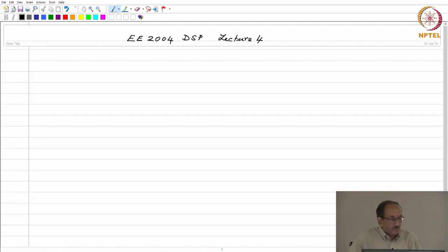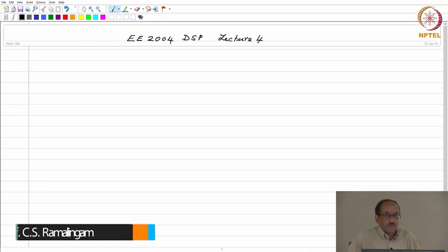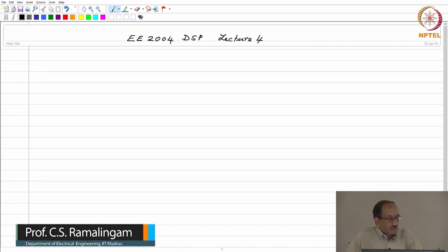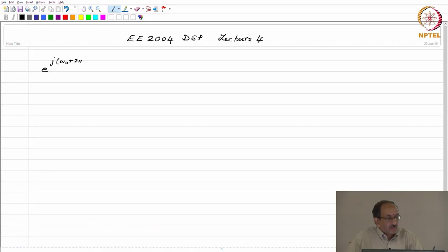Let's continue from the last lecture. So, we were looking at discrete time sinusoids, and the difference that we saw was e to the j (omega naught plus 2 pi) n was the same as e to the j omega naught n. Therefore, omega 1, if it is omega naught plus 2 pi, which is greater than omega naught, yields exactly the same signal. Even though the frequency is different, as far as the signal is concerned, you get the identical signal back.